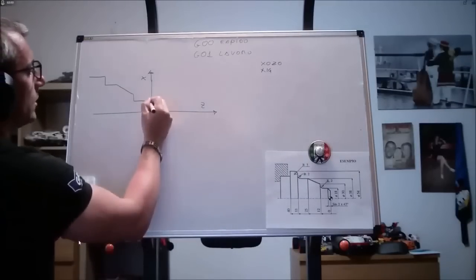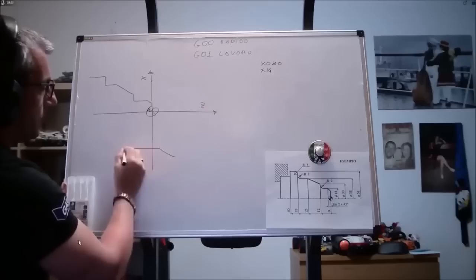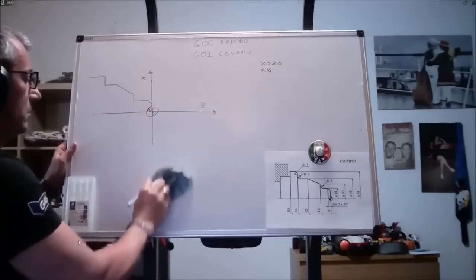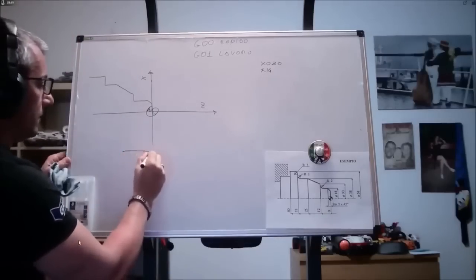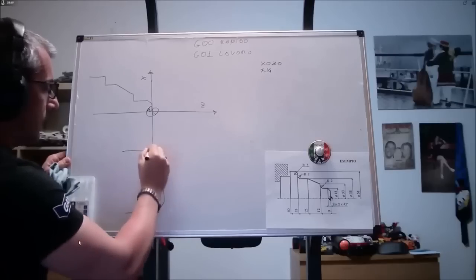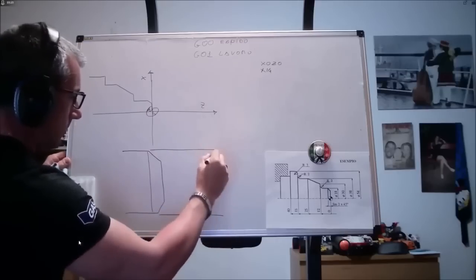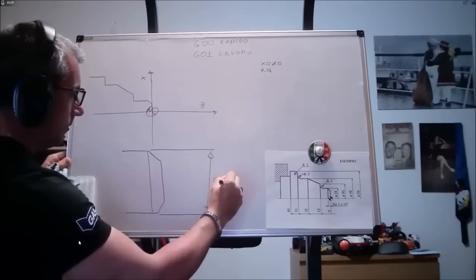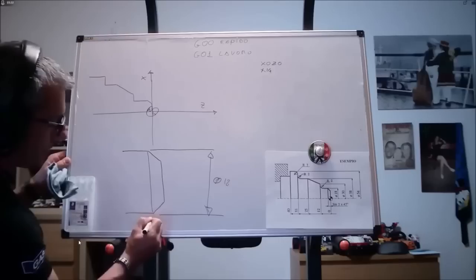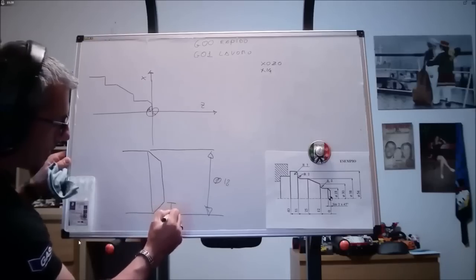So, since we have, let's exaggerate a bit for clarity, a chamfer, which is a transitional edge between two faces of an object. I have never drawn it for you before, but now I will. Imagine a piece made like this. This diameter is 18 millimeters. This distance from here to here is 2 millimeters, but also from here to here is 2 millimeters, and 2 millimeters also from here to here, because the chamfer is 2 millimeters at a 45-degree angle. This means that 18 minus 2 equals 14 millimeters.